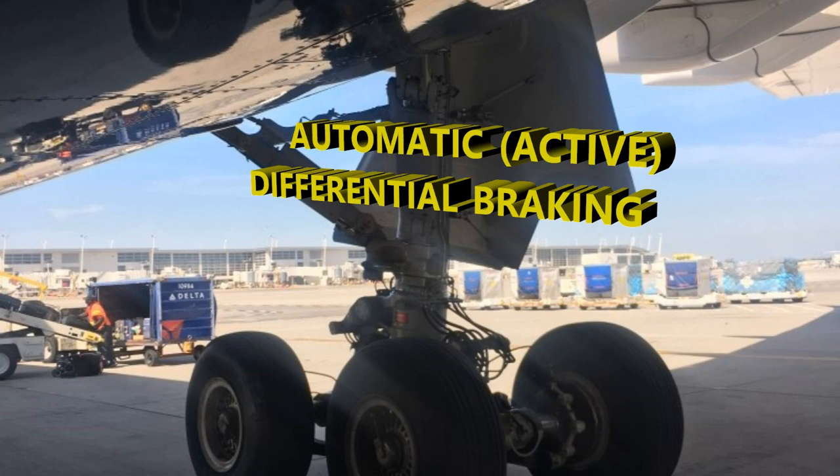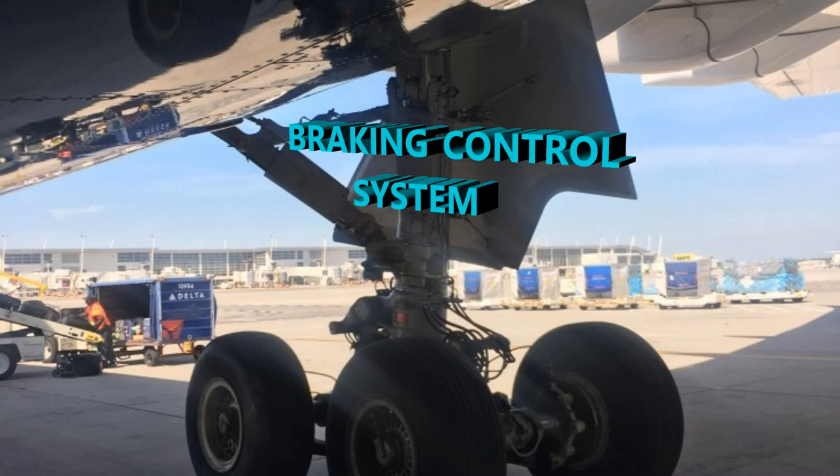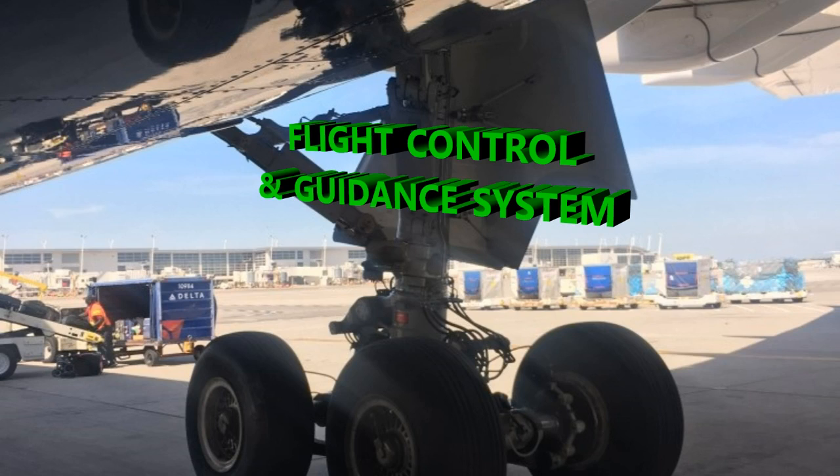Okay, so it's using the automatic aircraft braking system to command a differential braking situation, so it can move the aircraft. And there's three different systems that are involved with this differential braking. You've got the braking control system, that's your actuation of your automatic active differential braking, and then you have a flight control and guidance system, and that's for your control, and then your wheel steering control system.